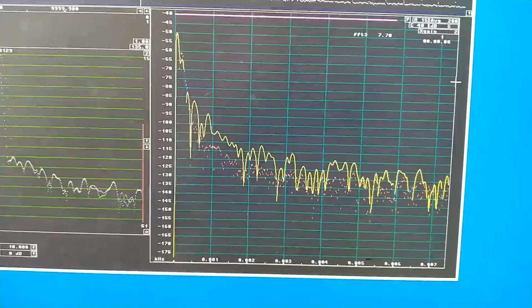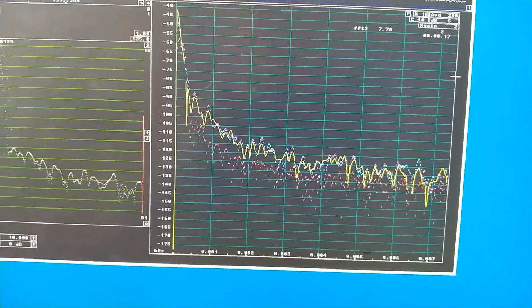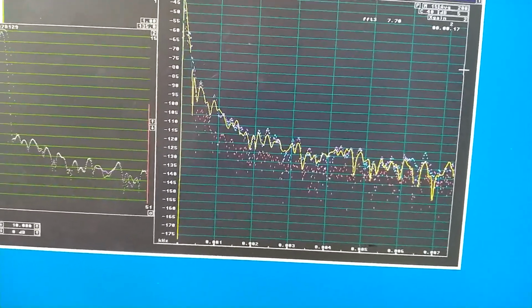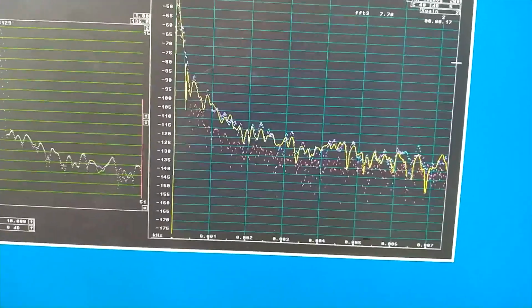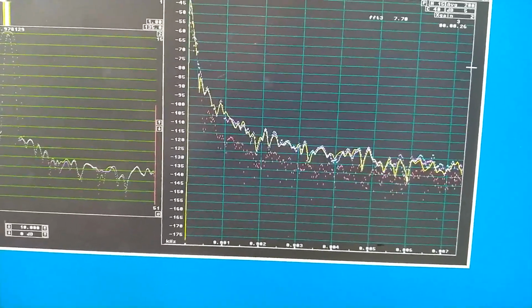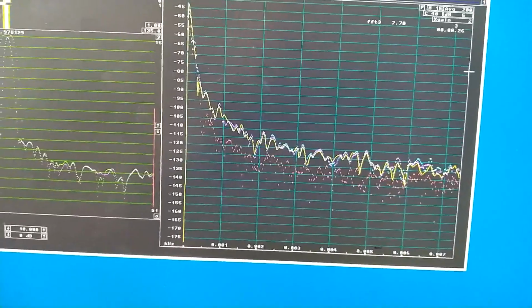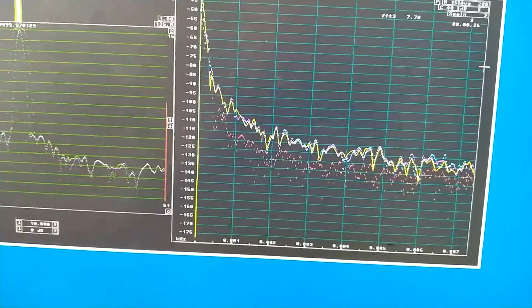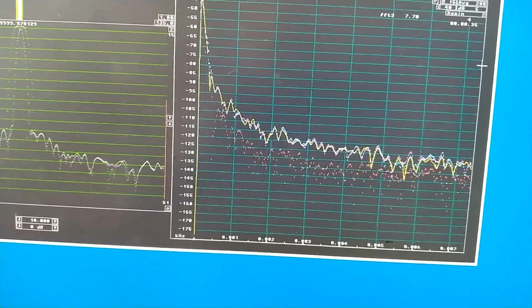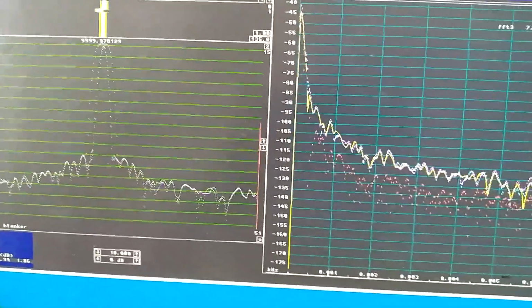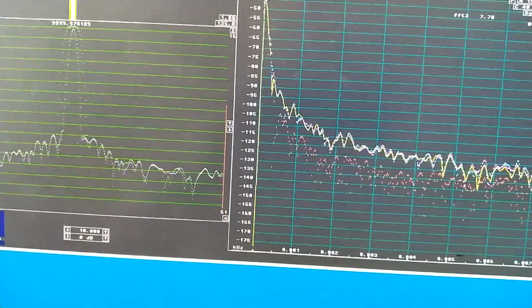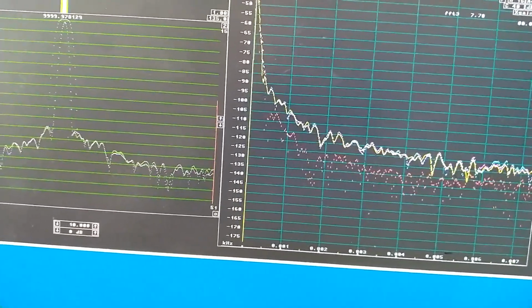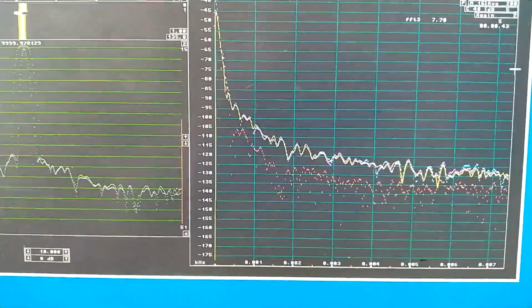So now I'm looking at the sine wave output. The level there is significantly higher, something like 3 decibels. And I set the Fourier transform size to 15, a compromise between the previous values. So it pretty rapidly will converge to a result somewhere around, it looks like minus 105 now.